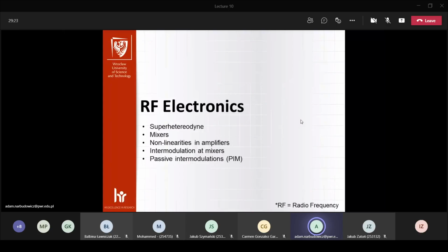Those are typically called linear components. And one of the characteristics of linear components is that they are not able to generate output at new frequencies that were not included in the input. Right. So if you take an RLC filter, it can filter out things, attenuate certain components, but RLC circuits cannot generate new frequencies that were not in the input signals from the beginning, right?